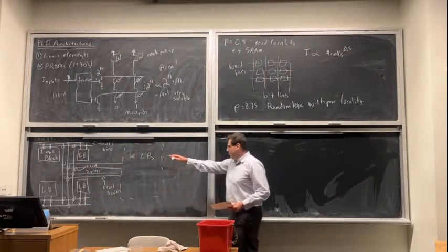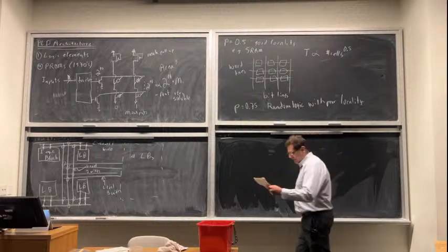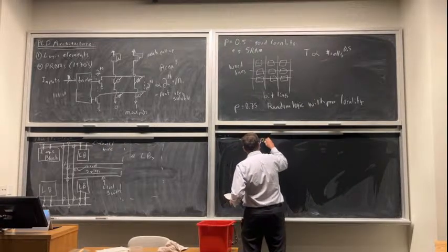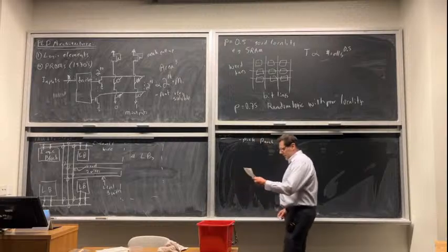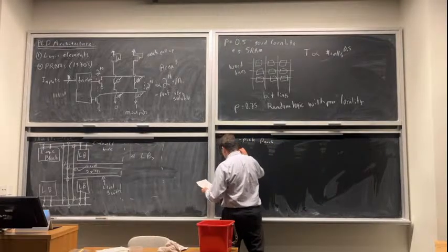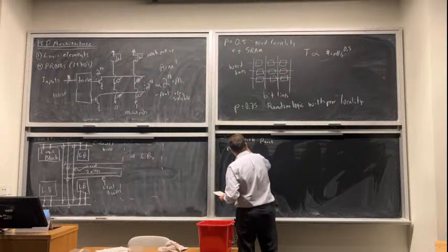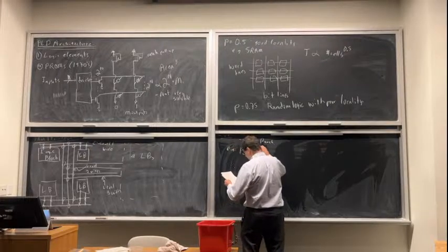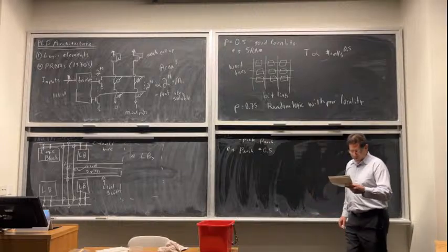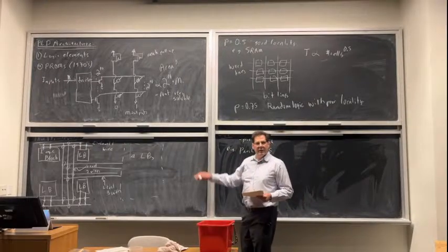So you have to pick what we'll call the rent exponent for the architecture. Let's say, for example, the rent exponent for the architecture is equal to 0.5. So I assume pretty good locality, and it's basically what I did over here.